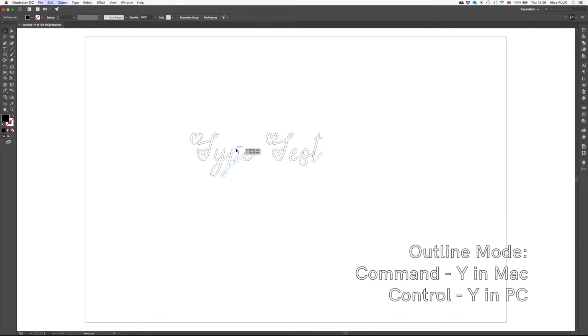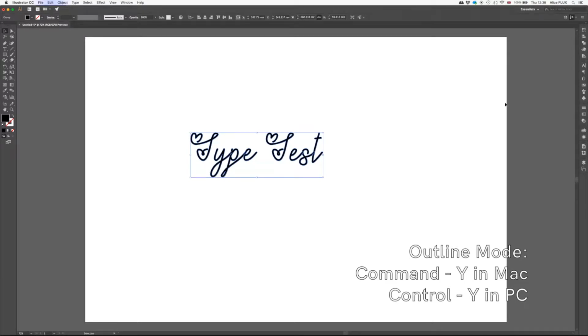With laser cutting and laser engraving, if something is overlapping each other, it's like a double negative. It ends up being positive. So what we need to do in this situation is make it so it's all one piece, so it's not got overlapping parts.